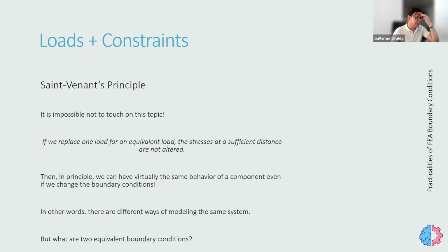So the interpretation of this principle is that we can have virtually the same behavior of a component in terms of its overall deformations and the stresses in the regions away from the boundary conditions, even if we change the boundary conditions.